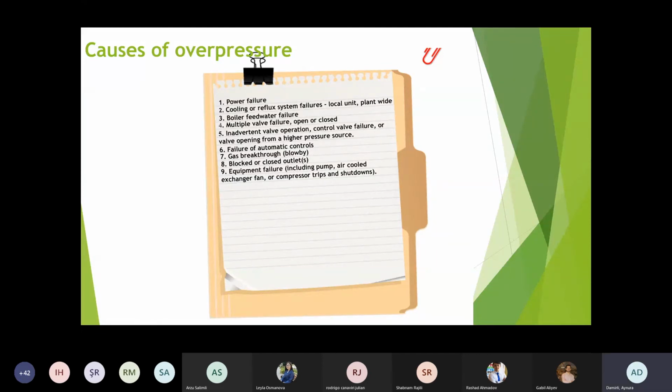Reverse flow, for example check valve failure. A reverse flow release scenario is defined as when a feed pump or compressor to a gas liquid system stops and the high pressure gas liquid can reverse flow into the lower pressure system.